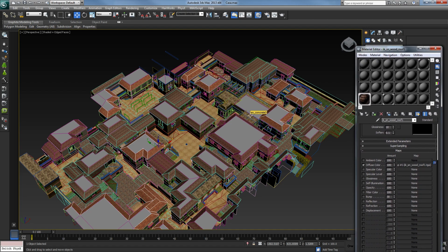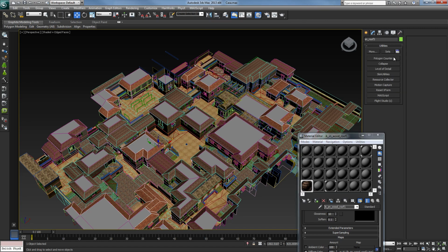So once I've established my material chain, of course, is to correct the materials themselves, and that is to consolidate the materials into a single folder. And 3ds Max has a feature for that called the resource collector, so we can collect anything that is attached to the scene as far as materials go, wherever they may be, in Lord knows what directories, and consolidate them under one directory.